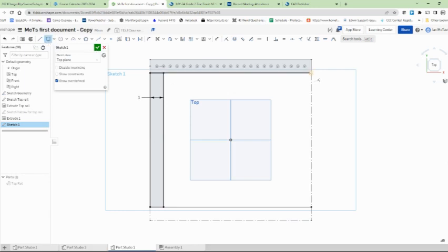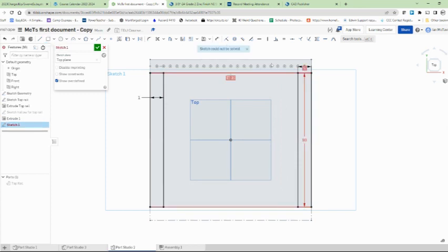So the corner rectangle, if I did a corner rectangle here, and I said that's 1 inch and that's 10 inches, you'll notice that's where I get my red, because what I'm trying to do is set it to be this length, but I'm trying to have it use those points as a reference. And it's saying those are two things. Right now they're the same, but what if I tried to change that? And it tries to eliminate any possibility of over constraining.